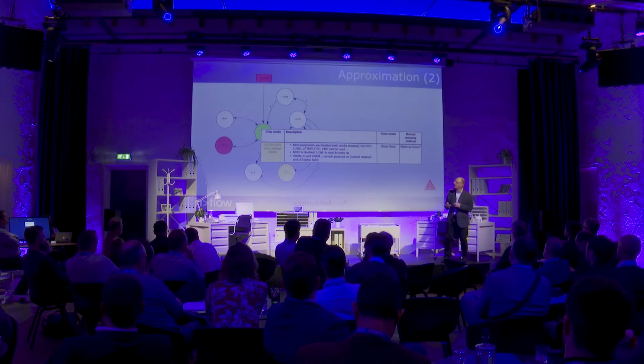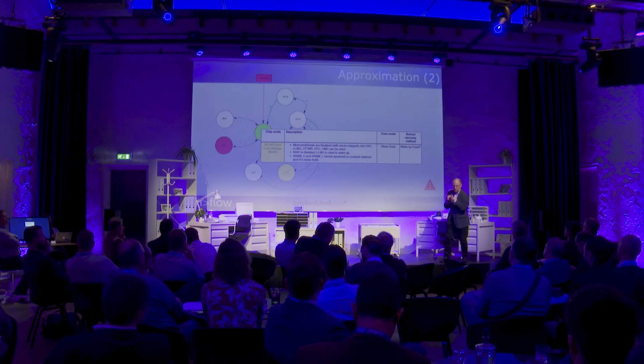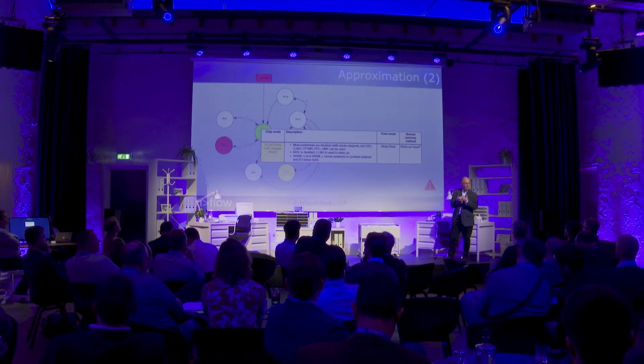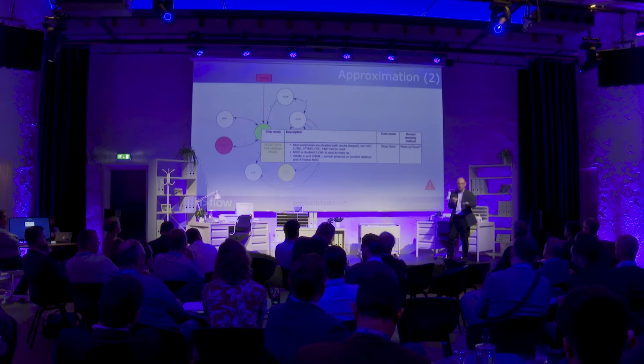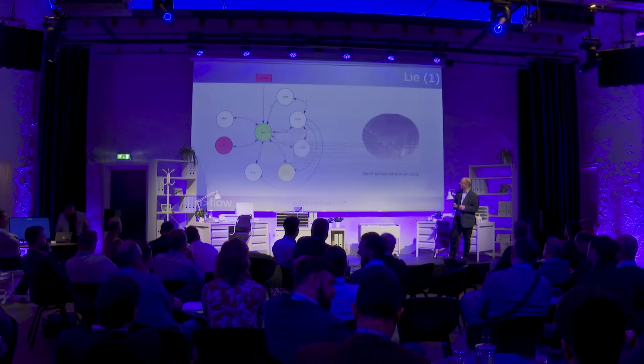It's fiendishly complicated. So that's an approximation that we have to take, which is, I'm going to guess a stop mode that might be relevant. But down the line, if you find that it won't wake up on the sensor in that mode, or all the RAM contents were lost, you know, we have to do more work to wake up. We have to go back and rescale our battery.